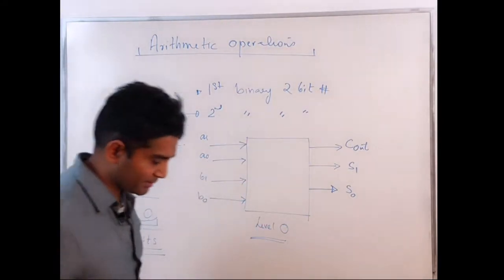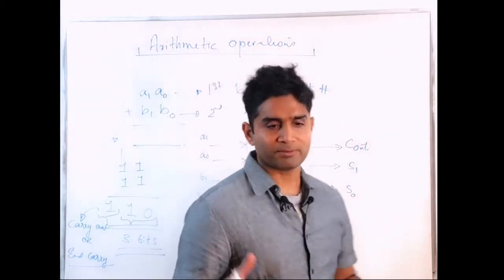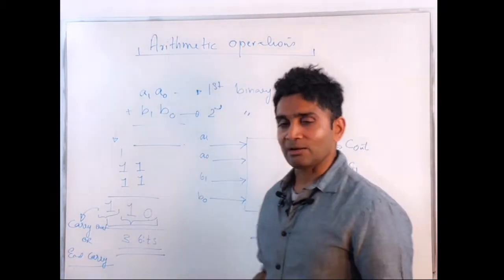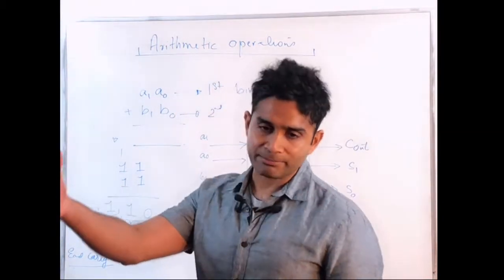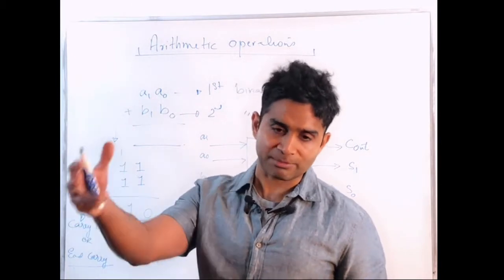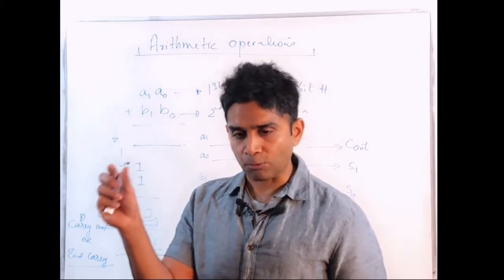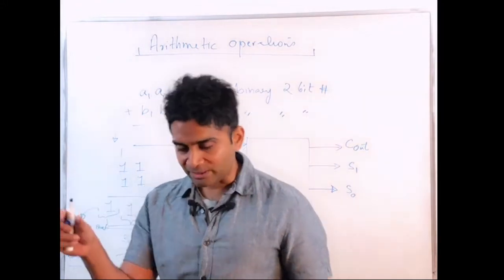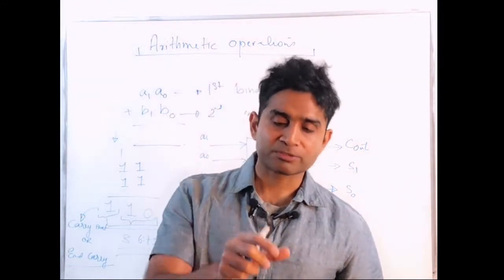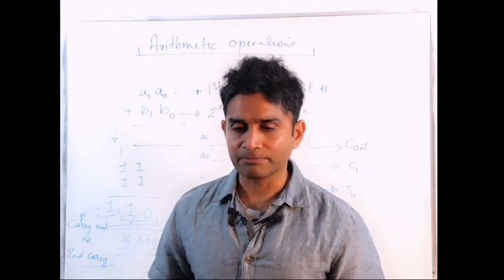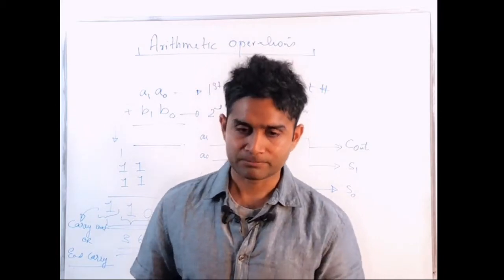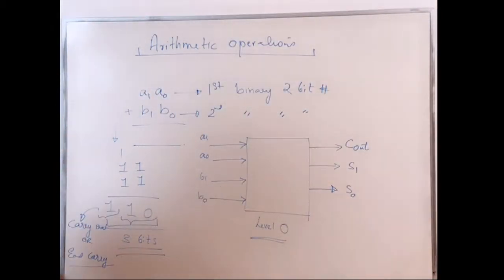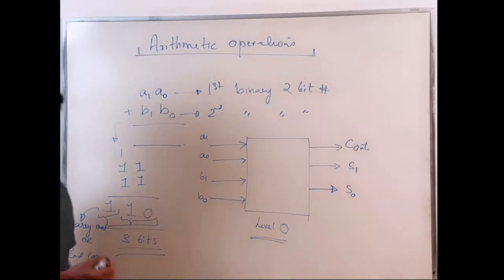I've done similar examples before when I'm trying to design a circuit that has multiple outputs based off of the same inputs. I would basically take each output to be independent and then find the function in terms of the inputs for each of these functions independently, and then I put together the circuit, and that's that. So I'm easily able to do that using the K-map approach.